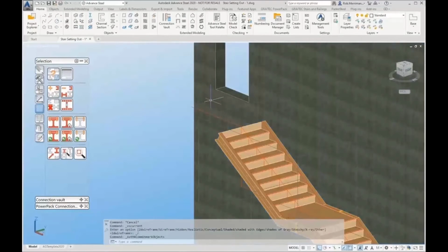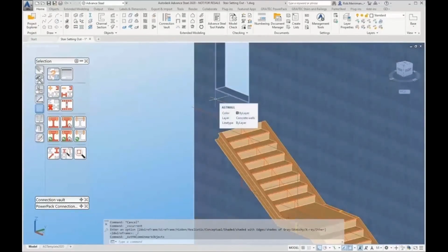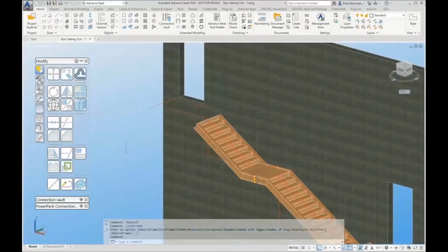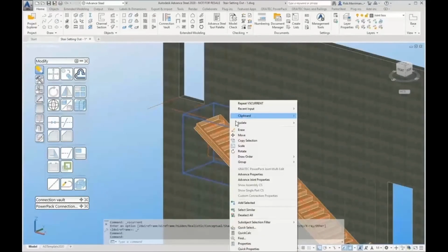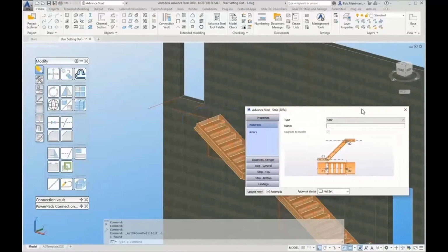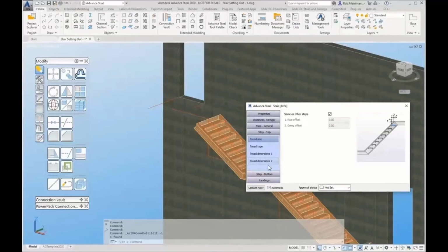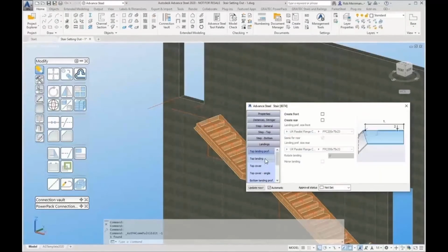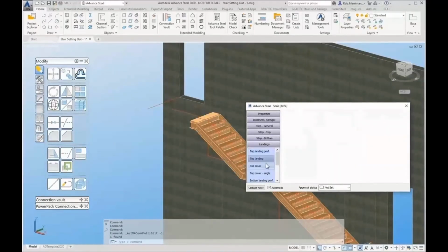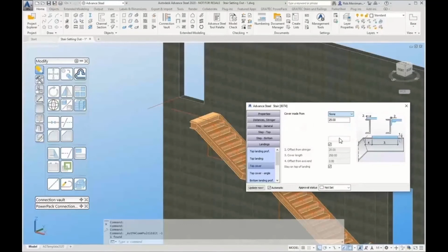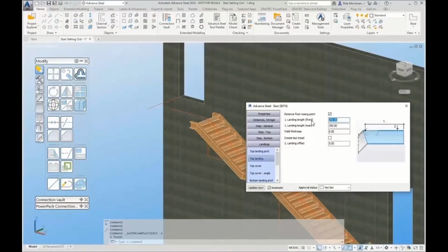At the top landing, we've got a return to the right, where it's going to go to that doorway. So we're going to build this up out of various pieces. So of course we're going to start with the stair macro to get as much as we can. So into the landing options, we're going to have, let's do both beams. Depending on how you want to create it, there's various options. We'll set the length, we don't want to cover. Right lengths.